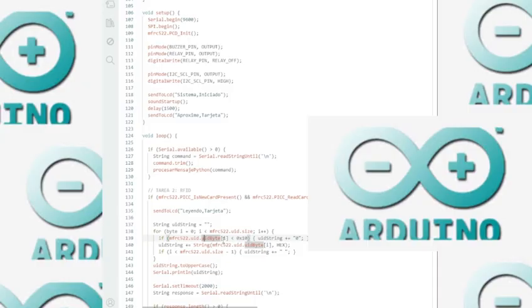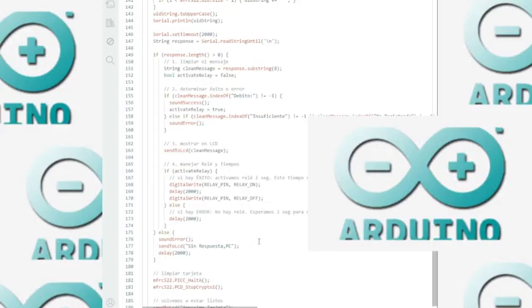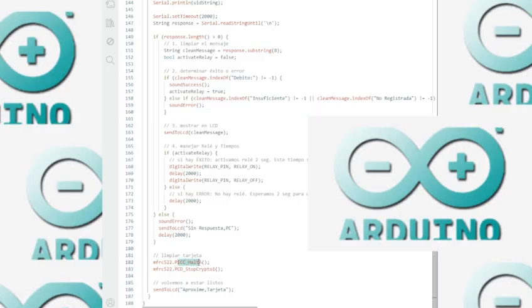The Arduino waits up to 3 seconds for a response from Python. Response analysis and activation. We analyze the response to determine success. A flag, wasSuccessful, controls the relay. This ensures the relay only activates after back-end validation. digitalWrite, we can see this here. And mfrc522.PICC_HaltA. Finally, we send a halt command to the card to put it in a halt state.